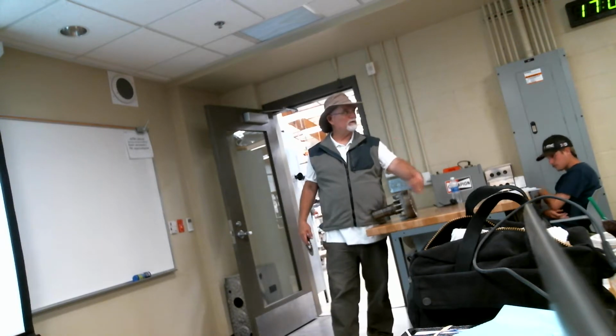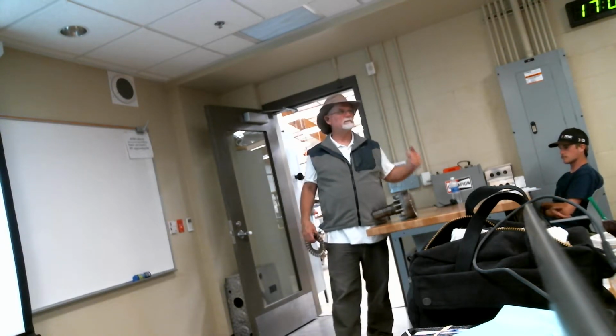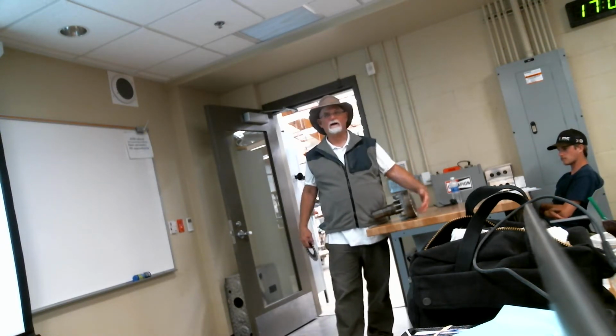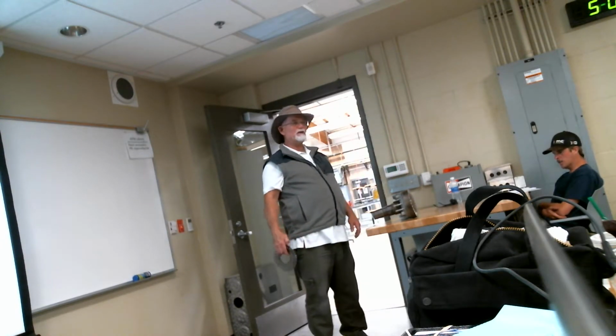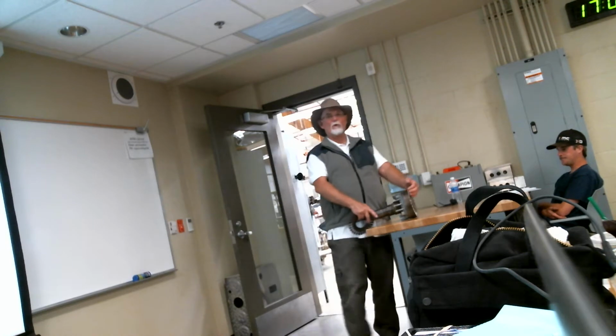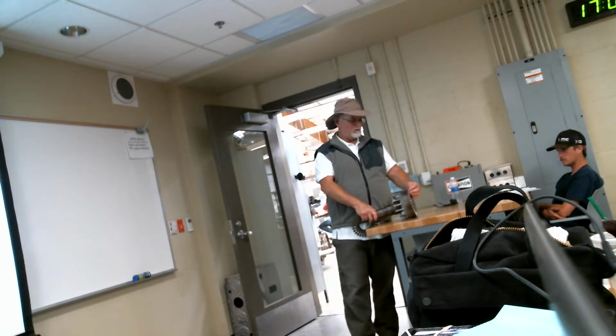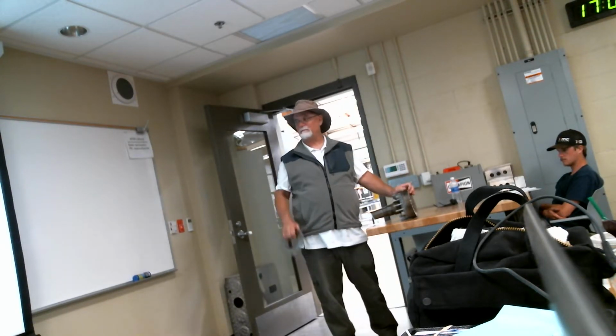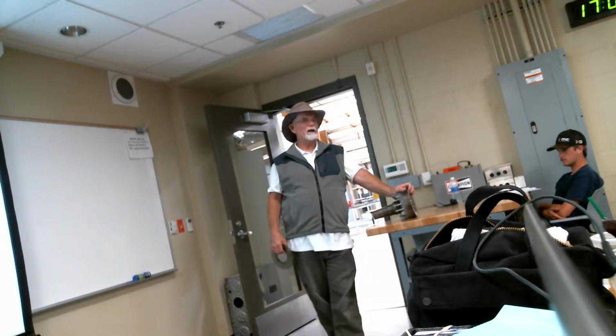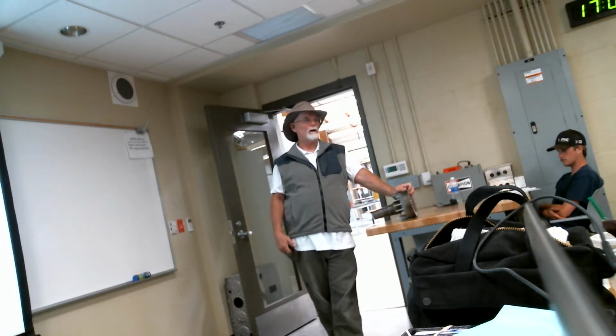This guy will start trying to follow those magnetic fields spinning around. If it ever catches up, there'll be no relative motion between this and the magnetic fields, so the induced current in here will go away. So it has to slip some. It has to slip some. Well, how much does it slip?